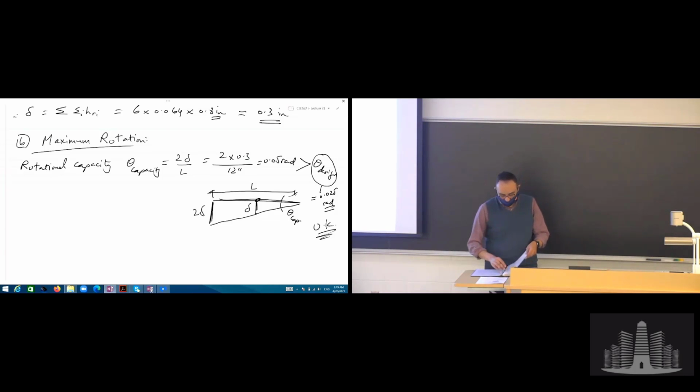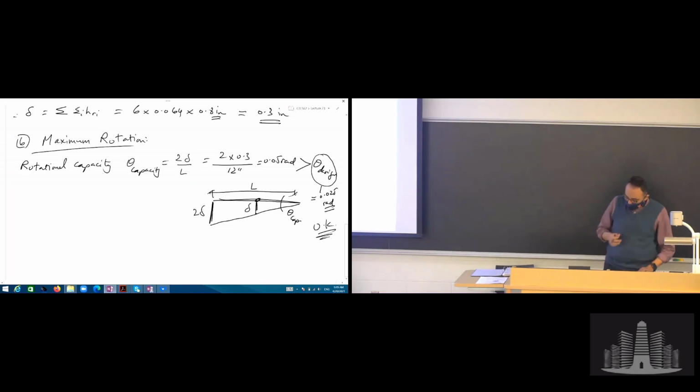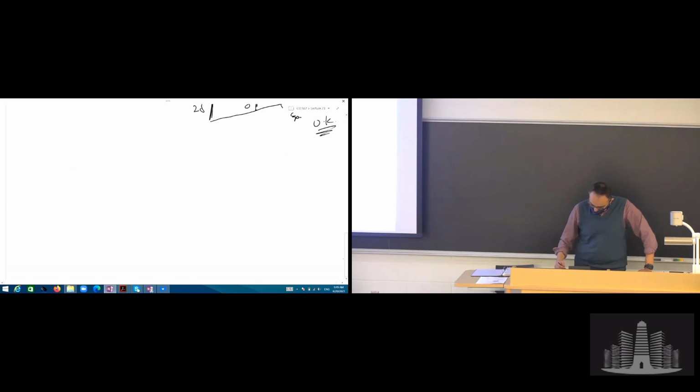Any questions, guys, about this? So now we have checked the rotation, and we have checked the vertical compression. All right. Step number 7. After we have done all this, one last important check that AASHTO provides is the check of stability. Given all the thickness and the dimensions now given to us, is it stable or not?